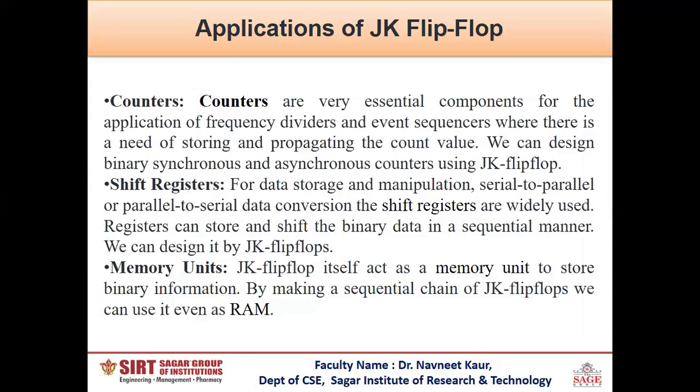Now coming to applications of JK flip-flop: counters. JK flip-flops are used in the designing of counters. Counters are used for counting of the sequences. So we can design binary synchronous and asynchronous counters using JK flip-flop.